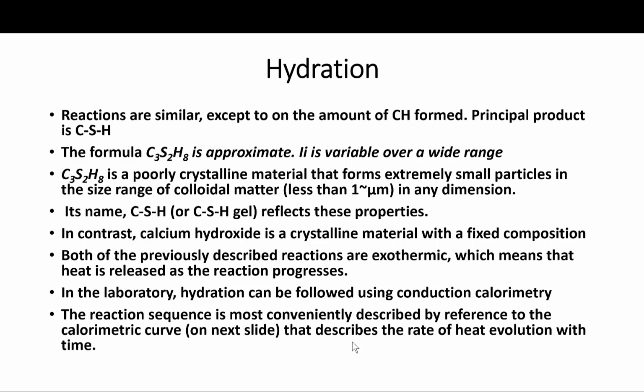As I said, the principal hydration product is a calcium silicate hydrate, as I have shown in the previous slide. The formula C3S2H8 is only an approximate formula, because the composition of this hydrate is actually variable over a wide range.